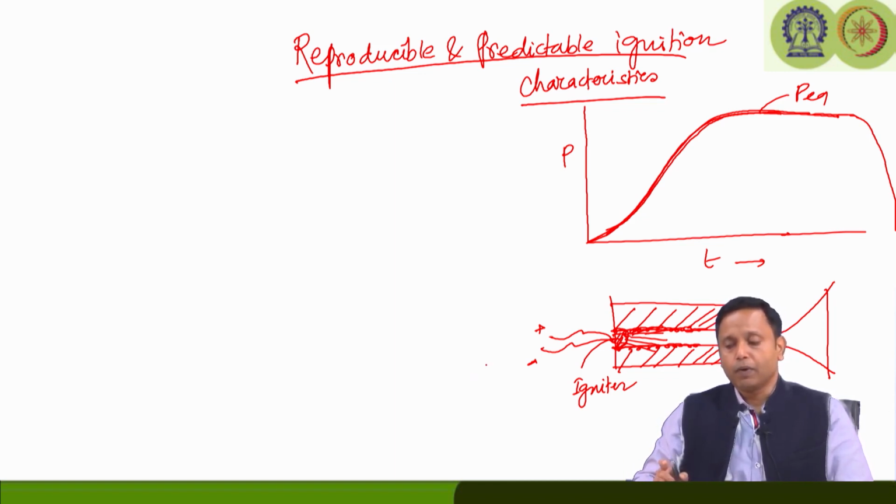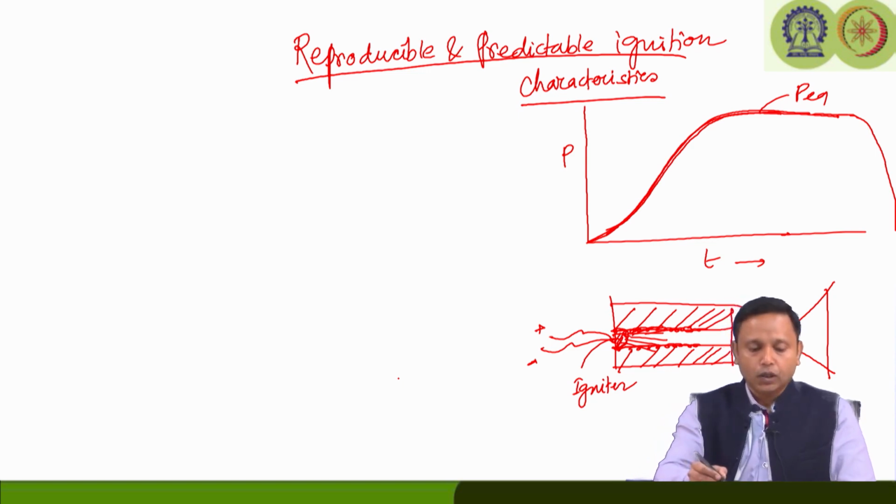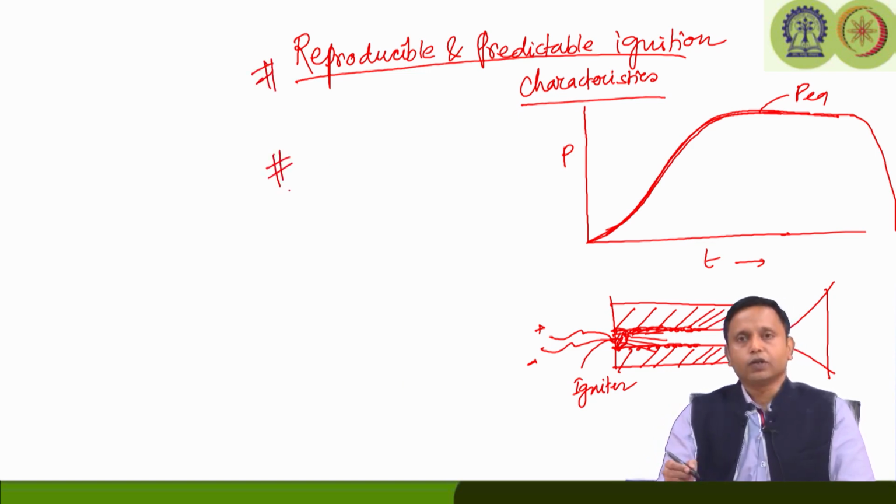Okay. There should not be any abrupt ignition or any kind of unevenness in the ignitions once we repeatedly test it. The other criterion, of course, is that once we make a propellant grain, it does not mean that we always use it immediately. Okay. So, we may need to store it for future use. So, the ingredients should be good enough that it maintains certain aging characteristics. I mean it needs to have long life and good aging characteristics.